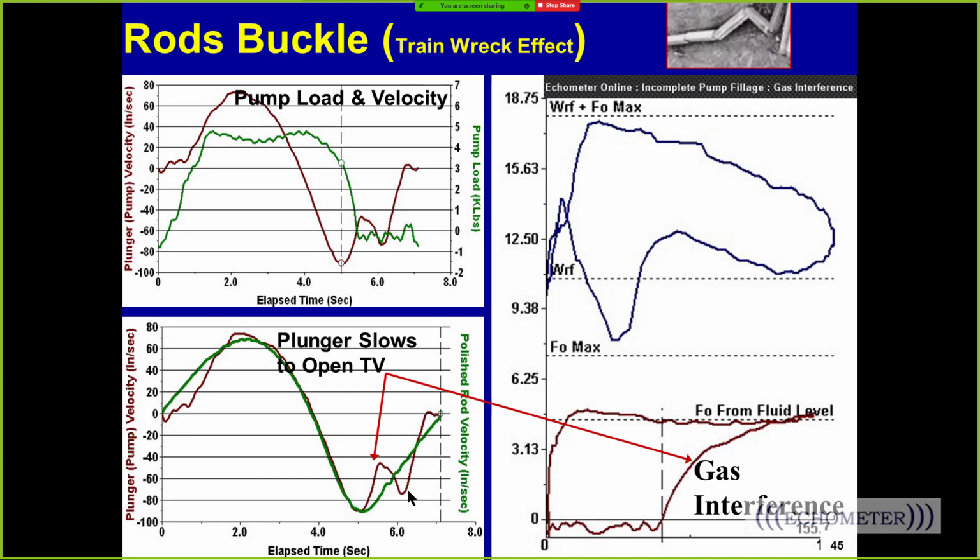So if you use a PRT, the card sits on 0 based on that point right there, and that's probably okay for fluid pound, for gas interference, for blocked intake, because over here where the pump's not moving, it works just fine. There's not a problem. The main problem is where you have mechanical friction. Then the mechanical friction becomes the zero load line, and that's not correct.